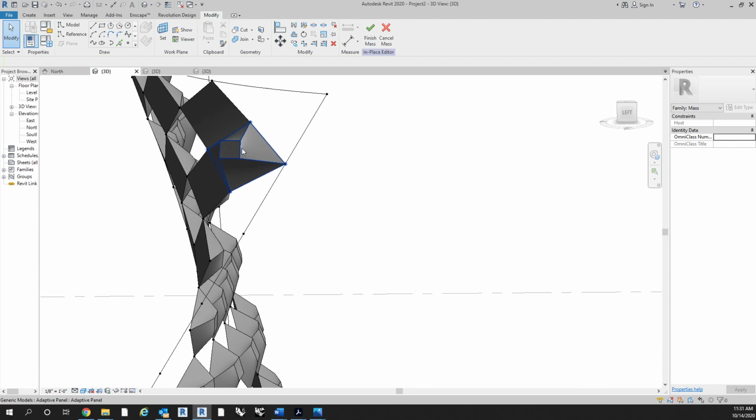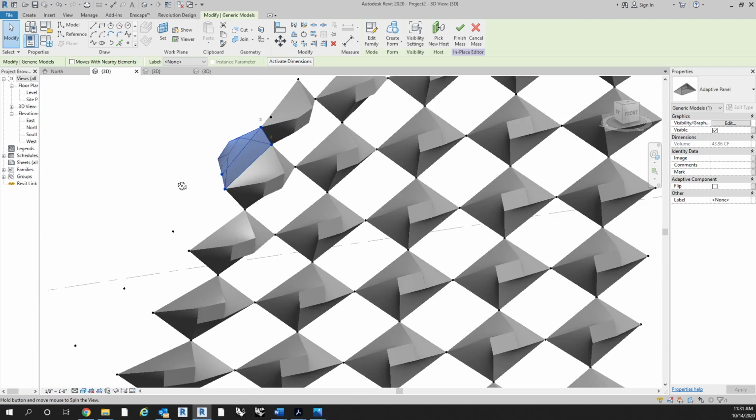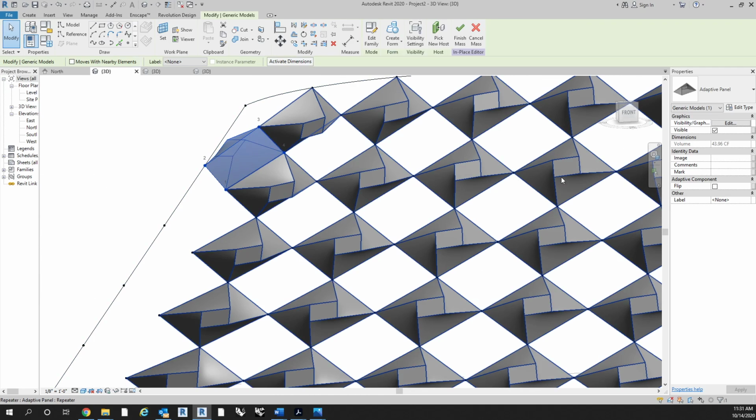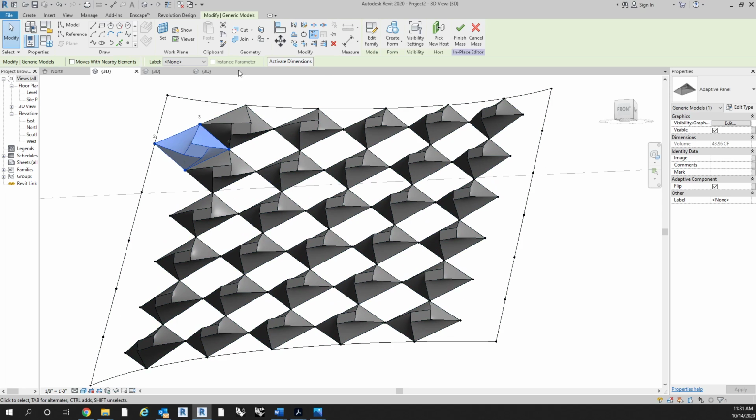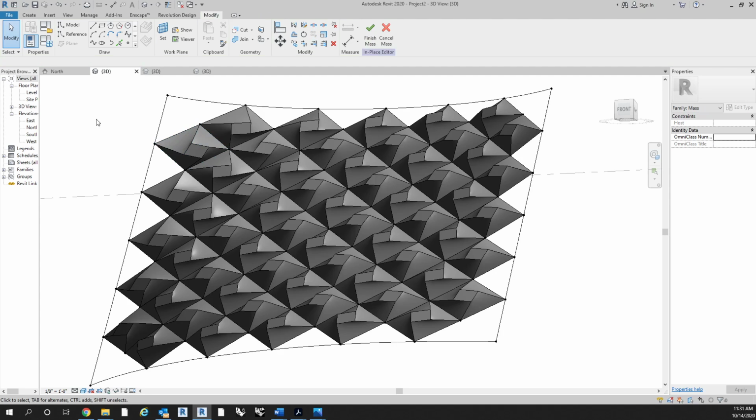Of course, that will then put this on the opposite side, but all you need to do if that happens is go over to the right side to the properties and hit flip, and it'll flip it to the other side. And then once again, hit repeat. It will repeat that across the facade at every instance, so it'll infill.